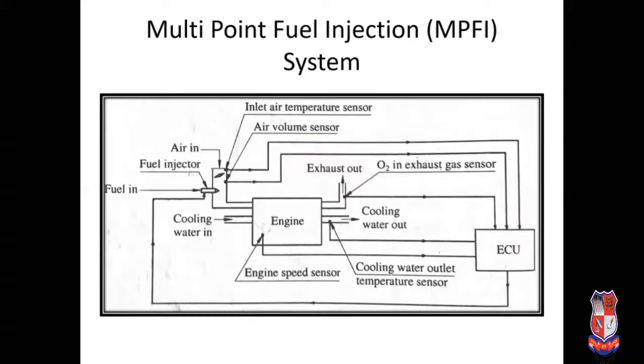A disadvantage of the MPFI system is that the cost is very high because different sensors are required, which are very costly. Then next, major parts are electronic, so they cannot be repaired, which increases the cost of maintenance. And the next disadvantage, skilled workers and special service equipment are required for diagnosis and maintenance. And obviously, the system is more complicated, which requires more care and attention.